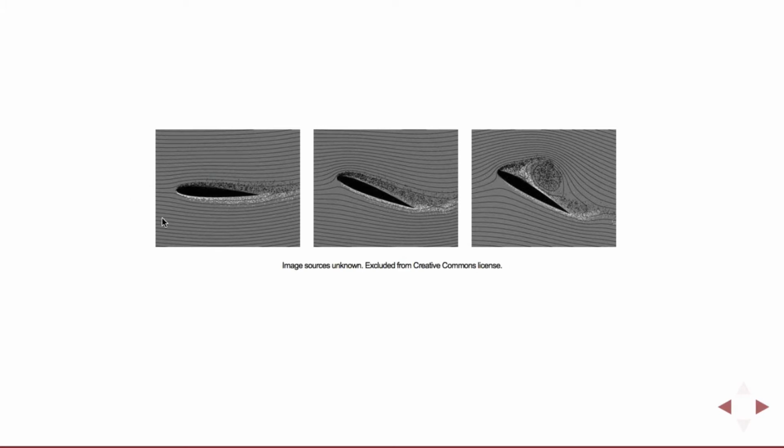All right, so just to tell you why this is hard: if you take an airplane wing and make it fly forward in air, when the wing is at a low angle of attack relative to the oncoming flow, the air bends around the wing, and piecewise linear models of the fluid dynamics, of the lift and drag forces, work very well. If I were to change the angle of attack of my wing relative to the oncoming flow, if I were to pitch my nose up as I fly, then the air still bends around the wing, and in fact, linear approximations of how the lift and drag change as a function of my angle of attack or my control inputs work very well.